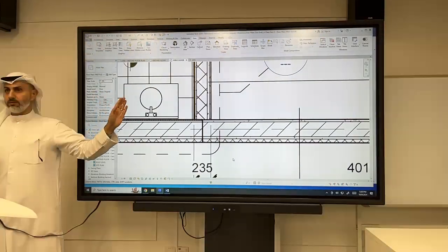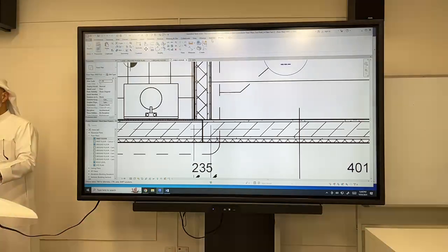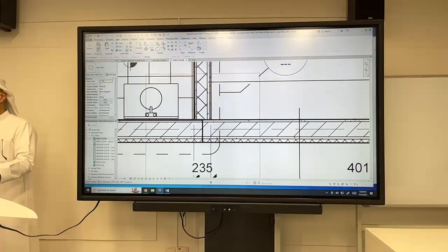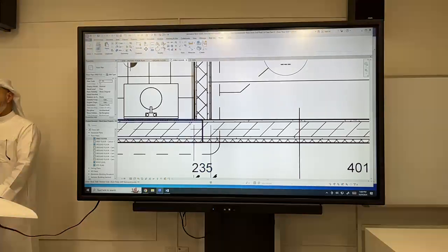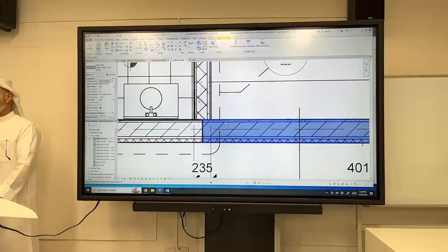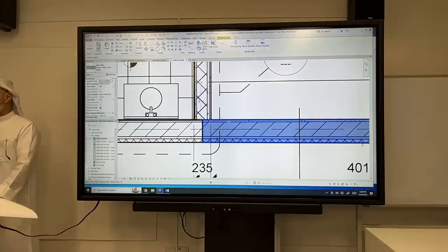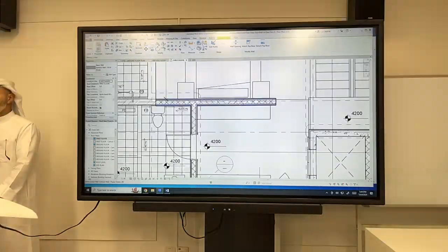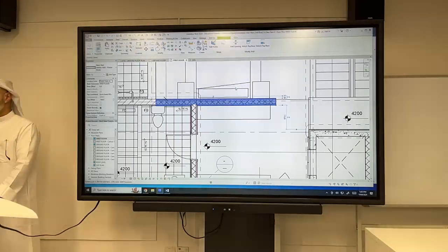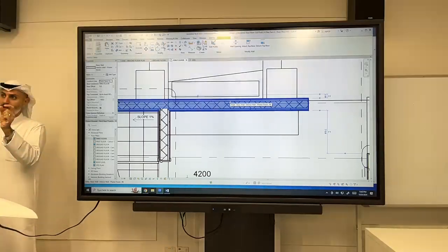Even though I split at the core, that's not what I ended up seeing. Okay? Click on Modify, Wall Join. When I changed the material of the brick finish for the bathroom, it became very loose if I didn't change this brick. This is plaster. No, this has to be exterior. Plaster finish interior, between the closet and the bedroom. This will become smaller because we're using 15 cm core and paint. That's why it's a lot smaller.